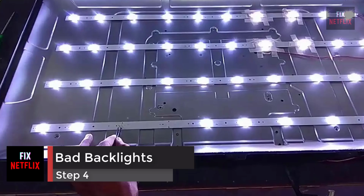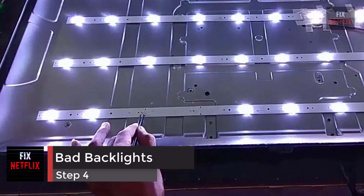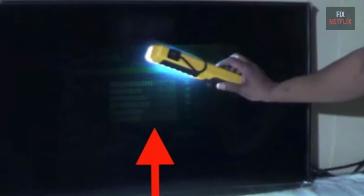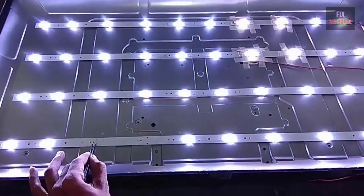Step 4. Bad backlights. This quick test will help you determine if the backlights on your TV have failed. Turn on the TV. Shine a bright flashlight at a slight angle to the screen. If you do see an image, this is a sign that the backlights have failed. The presence of the image means everything else is working properly.